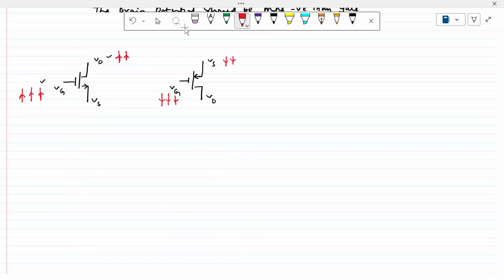If the drain potential of the NMOS transistor is decreasing more and more, then what does it mean? It will enter into the linear region. If the drain potential increases more and more than that of the gate potential, it is in the saturation region.